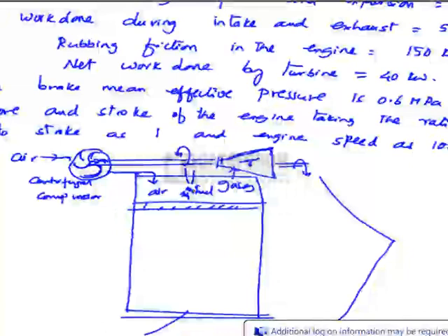the gases are formed doing work, and the exhaust gases leaving the cylinder drive the gas turbine, and the turbine drives the centrifugal compressor. This is the actual setup of the turbocharged diesel engine. The turbine drives the compressor. The turbine in turn is driven by the exhaust gases leaving the engine cylinder.